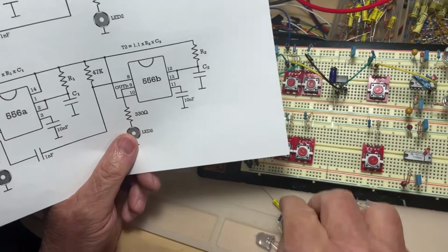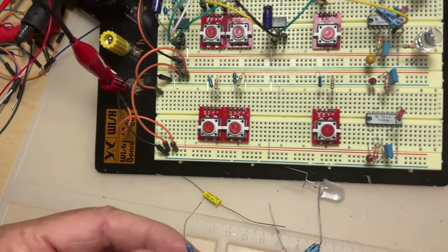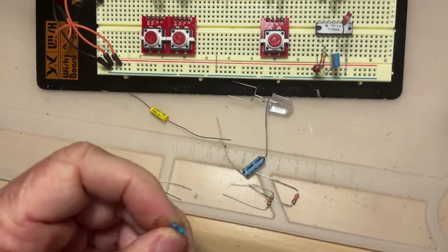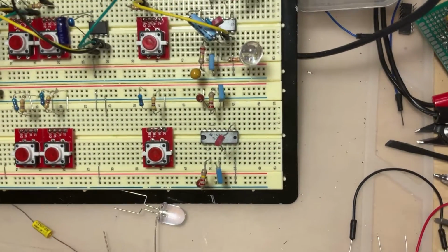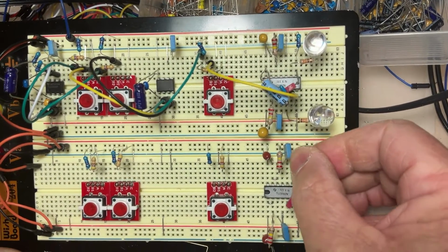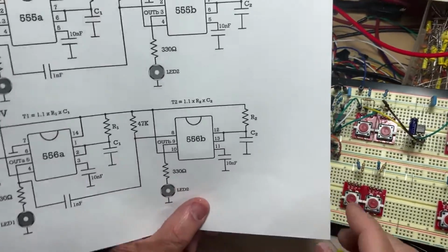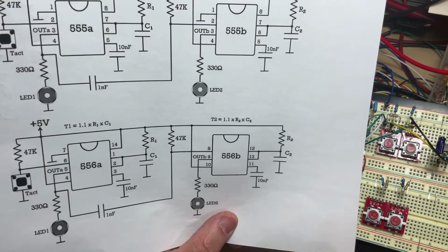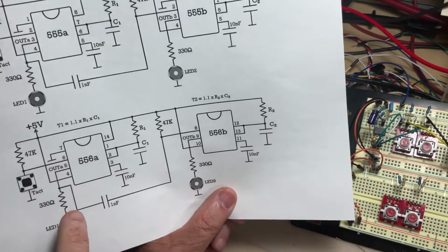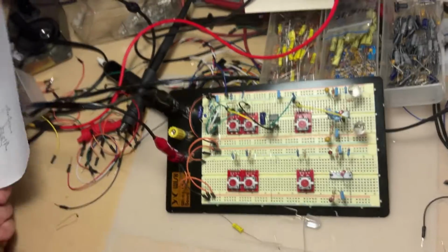And also, to trigger, you need a 47 kilo ohm. I have it over here. Even if you can't see the colors very easily because it's a darker body, it doesn't matter. So I'm going to place it between the pin 8 and the positive. So this is done. So now what's remaining to do? Two things: to connect the push button to trigger everything, and then to have the LEDs connected.